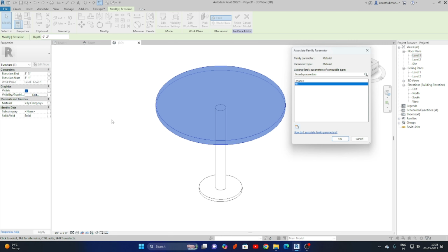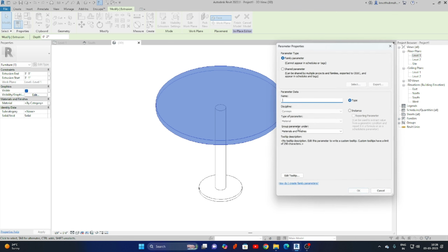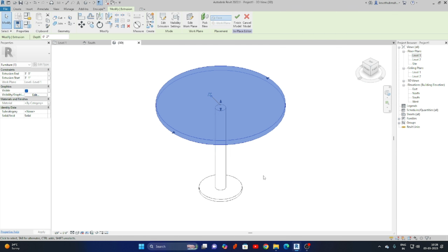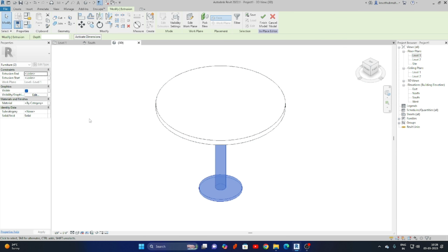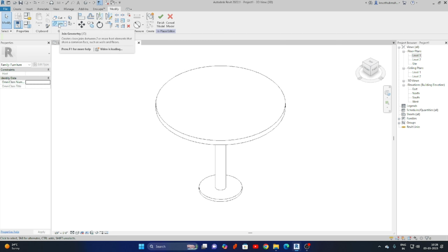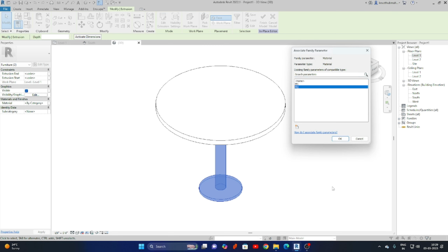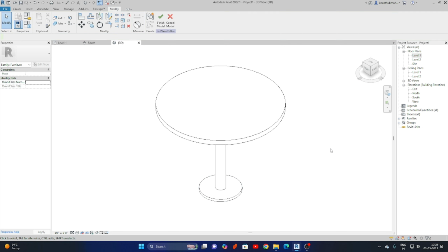And you can select this one again, go to the material, you can give it, or otherwise you can create the second material also here. Again I will create, so it is material 2. Okay, instance. Next, now I will select M1, click on OK. Now I will select both, or you can choose one more thing, join the geometry. I want to join this with this one. Okay. Next, cancel it. Now I will select this. No need to create it, simply select that material, we have already created it. So select. Now it is done.